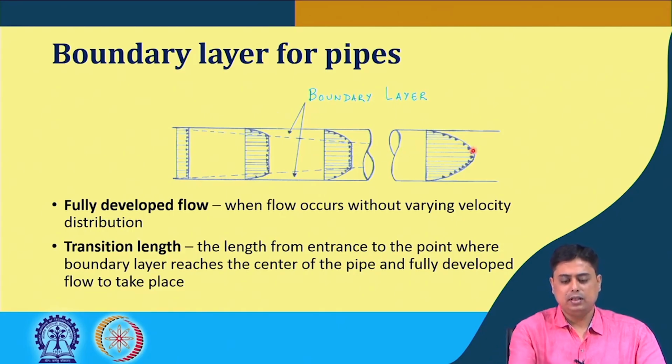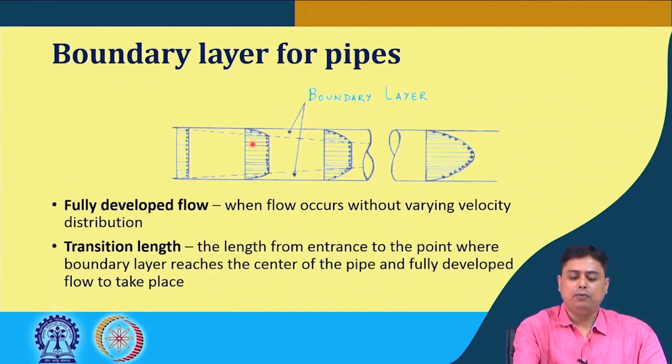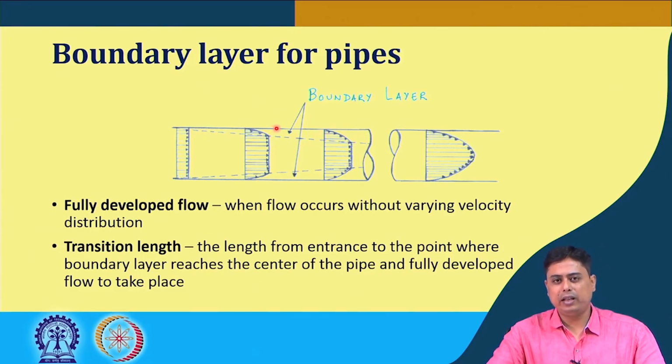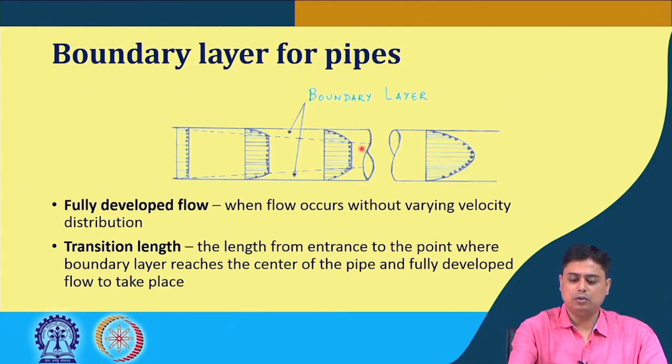So, what happens is that as soon as it enters, the boundary layer starts to develop, okay, and in the developing region, the fluid flows like a rod kind of a behavior, because here the fluid movement is there and here the boundary layer. So, here the flow is very low, as you can see that we can understand that in the boundary layer we have seen there is a laminar flow or the viscous sublayer, buffer layer, and then the turbulent flow or the flow of free stream region comes into play. So, there is a substantial